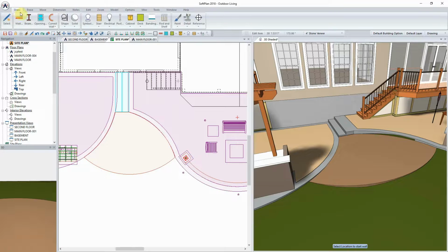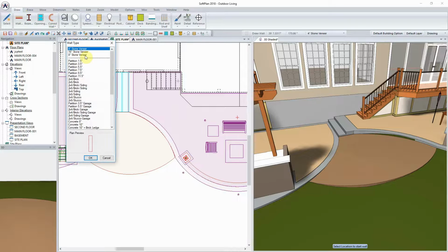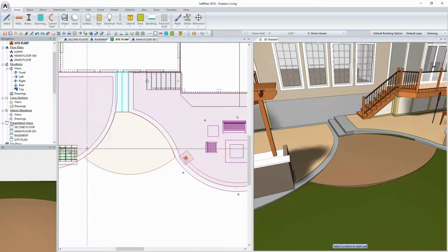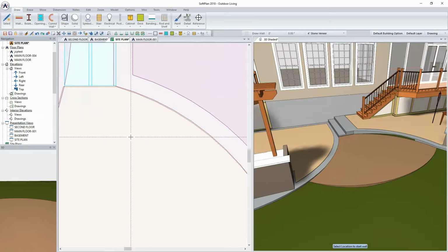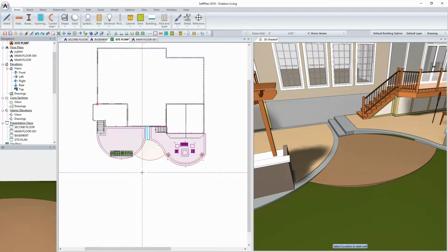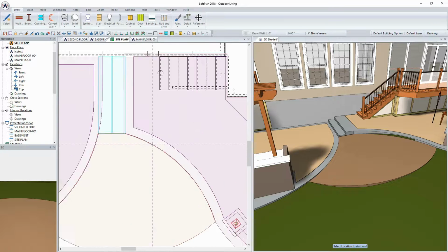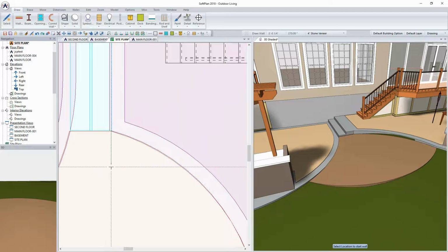And so at this stage, I'm going to select draw, and when I select curved wall, I'm going to pick the start and radius. Selecting that will give me access to the wall list, and the various wall types that are available or have already been drawn on the site will be listed at the top. And so in this case, I'm going to select this 4-inch stone veneer, which I used earlier on the kitchen. And so as I zoom this up, and this is actually kind of a valuable point, notice that when I'm drawing this, I don't stay at this zoom scale, which makes accuracy in picking my start and end points much more difficult. But rather what I will do is zoom up where I'd like to start a wall.